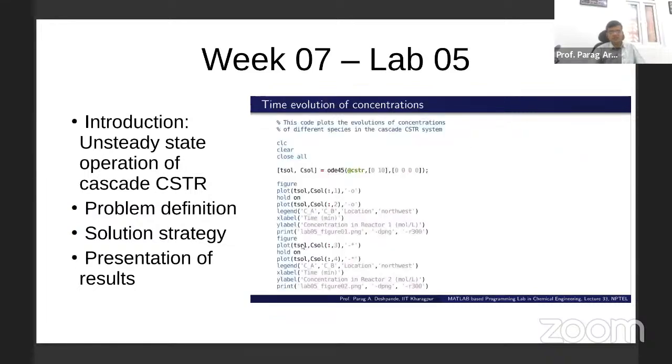These all unknowns become the components of the vector and the vector becomes the unknown. Right? So here, if you compare the syntax, it remains unchanged. But then you have to define instead of an unknown, a vector whose components are unknowns, and therefore initially when you used to give an initial condition, now you have to give an initial condition vector.